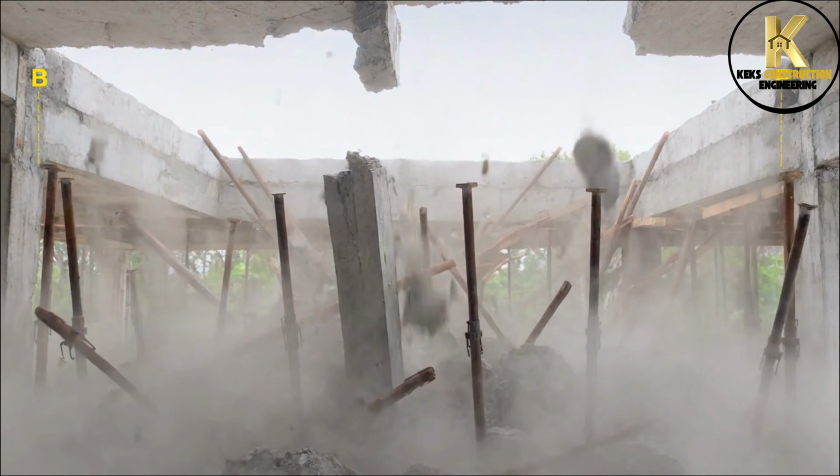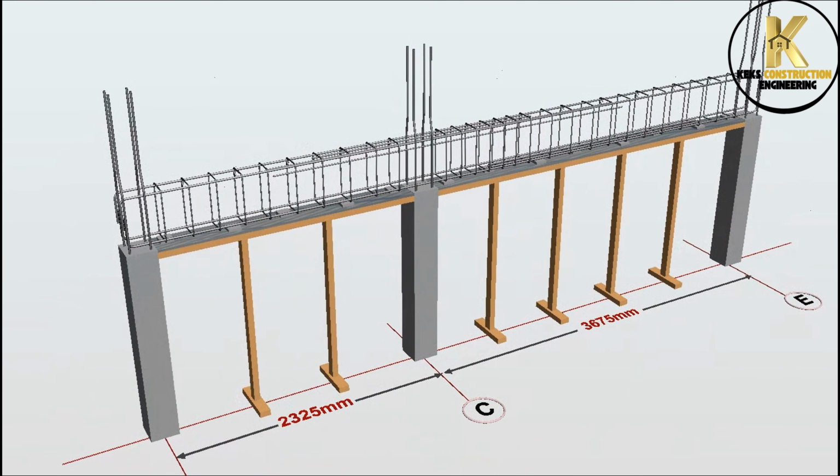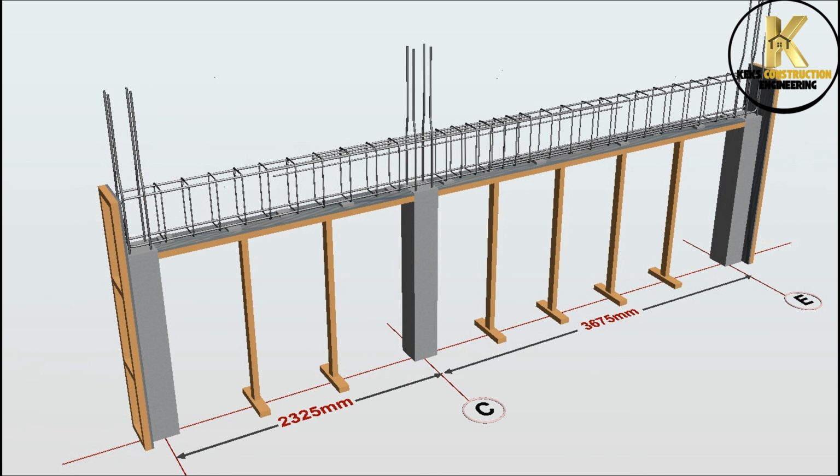Also take note, to ensure maximum structural integrity, you should lap top bars at the mid-span center of the beam and bottom bars near the supports columns where the respective tension forces are at their lowest.